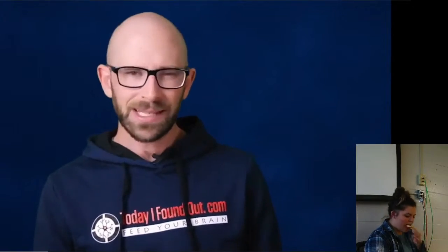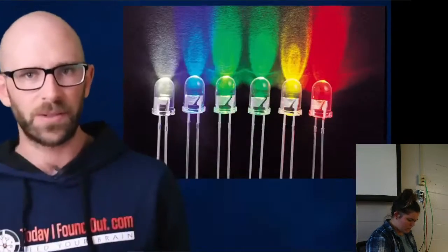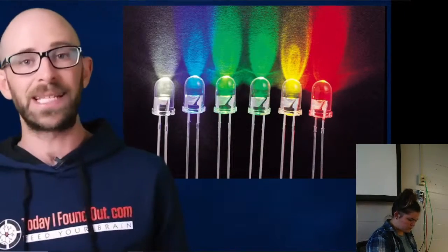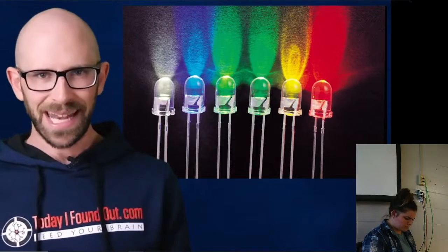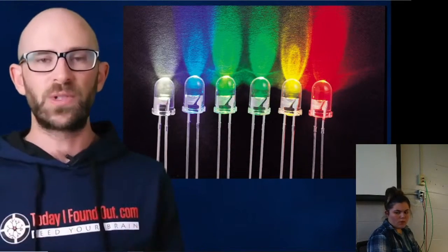So how are these diodes modified to produce light? Well, it turns out they don't really need to be modified at all to produce a form of light radiation. However, standard diodes tend to be made of materials that absorb most of the light radiation given off, and more importantly, tend not to give off light in the human visible form anyway. What's going on here is, as the electricity jumps across the p-n junction, the electrons from the n-type fill the holes in the p-type side. During this process, the electrons end up changing their state. During this state change, a photon is emitted.